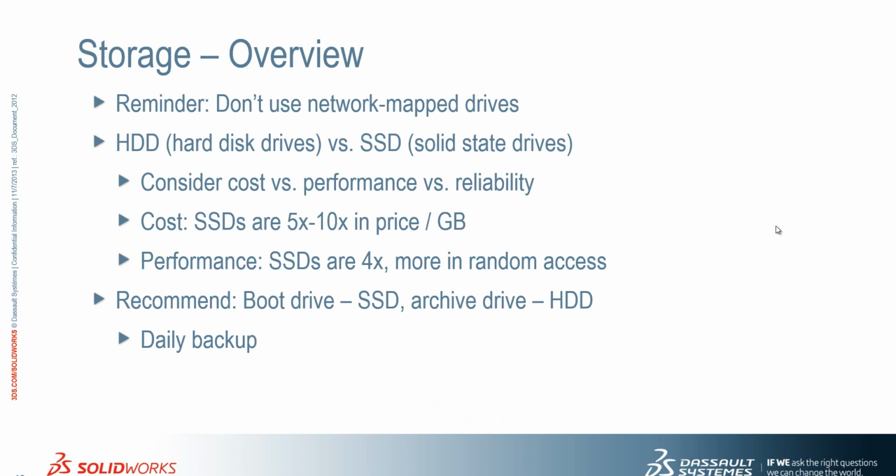So it's just an overview really. If you can, try not to use mapped drives. I know in some offices you all share the same data location. It is convenient, but as I say, it's slow. It is liable for file corruption over the network. If you think, well, how are we going to do it? Use a vault. If you've got SolidWorks Professional, you're entitled to a vault for free. For Workgroup, use that. If not, you can always use Enterprise as well.